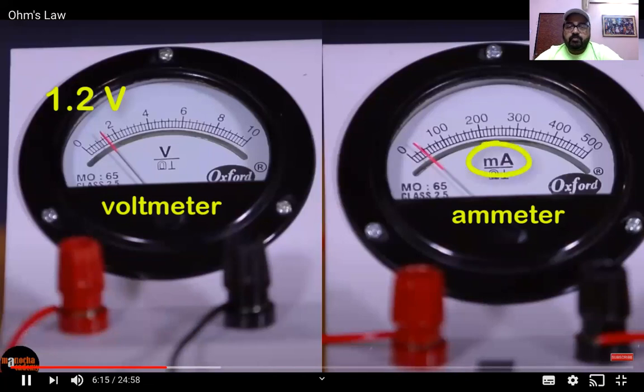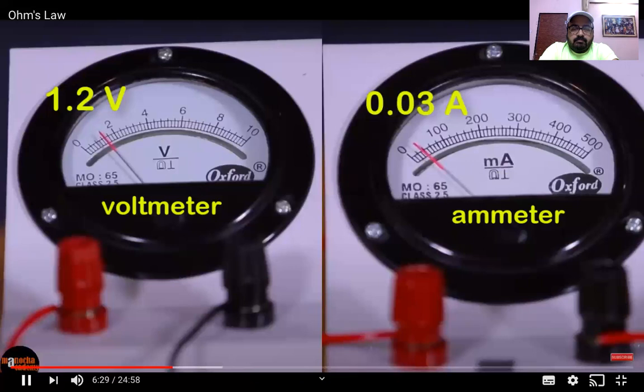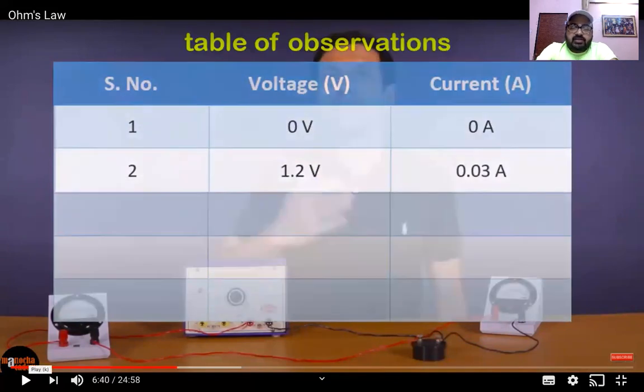Meter is marked in milliampere. The reading in the ammeter is 30 milliamperes, which is 0.03 ampere. Note that the wire does not get the full 2 volts from the voltage supply. The potential difference across the wire is 1.2 volts. This is our second data point. Let's add it to the table of observations. Now you can see that this is the table which I am talking about.